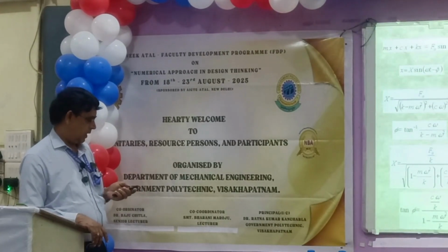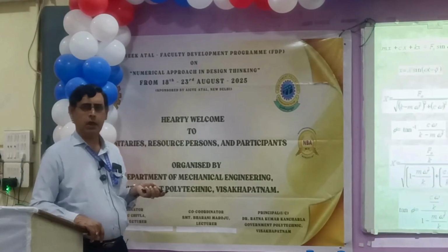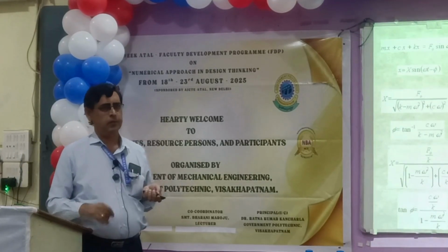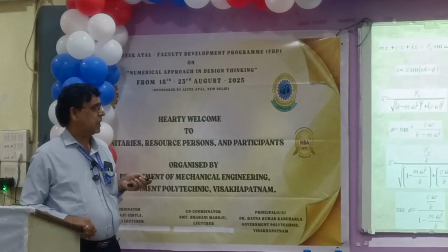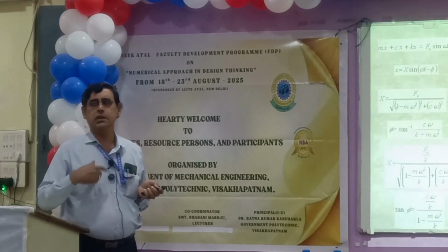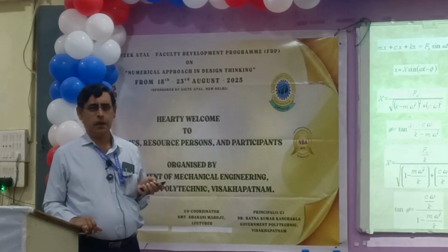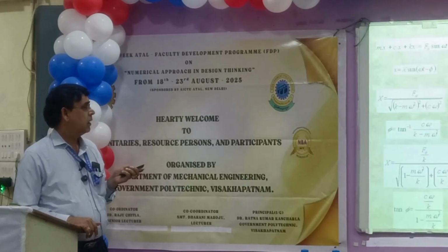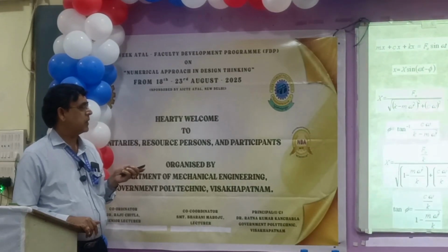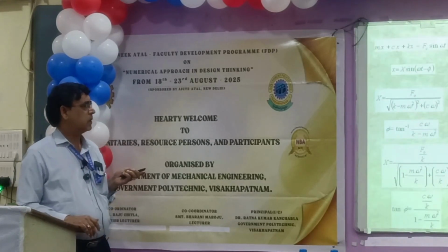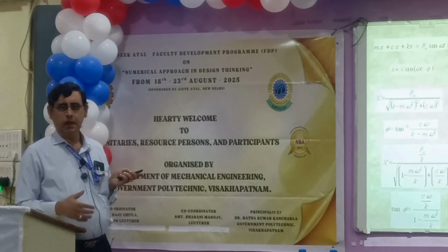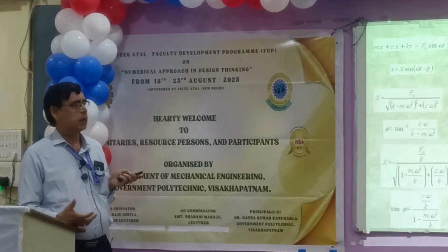Why I am showing this is, of course, you can always see this in any book on vibration theory. But it has relevance to how isolation is designed, because ultimately you have to design this particular aspect, the stiffness and damping in an isolator. Equipment is given as a mass and it is generating some force.